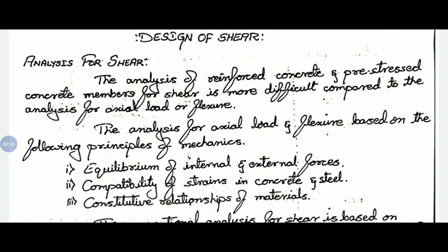So how we are going to consider the parameters, how we are going to analyze the members for shear, we'll discuss later. So before going to that, let us have some introduction about shear stress in PSC members. In analysis, we will consider the shear stress based on a few principles of mechanics. One is equilibrium of internal and external forces, compatibility of strains in concrete and steel, and constitutive relationships